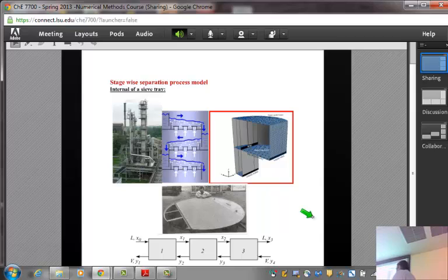For example, you have a lot of sulfur dioxide from the emissions in the power plant, and you want to remove the sulfur dioxide, and you're using a solvent. So you know y4, and you want to reduce it to y1, a known concentration, a very small value. So you treat y4 and y1 as specifications, and x0 of course is known, and you know how much of vapor you need to process, how much of gas you need to process, V. So you say, how much of solvent should I use to achieve this?